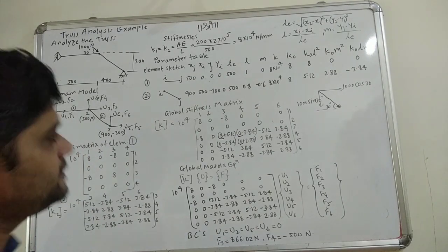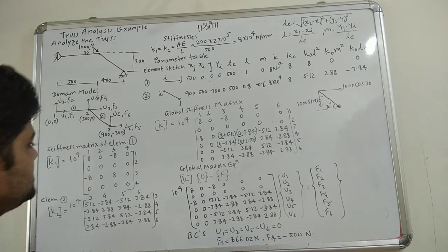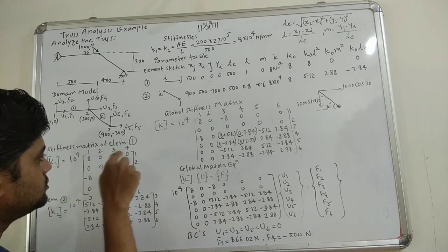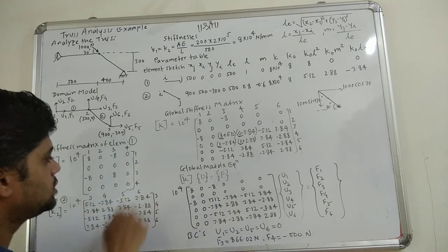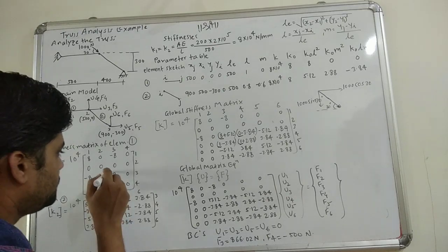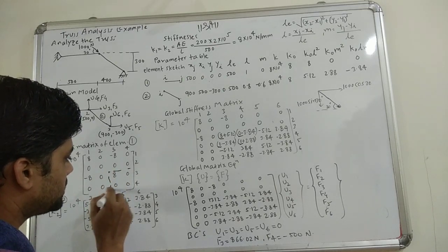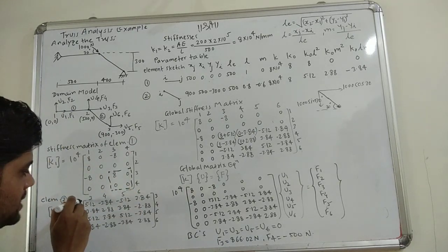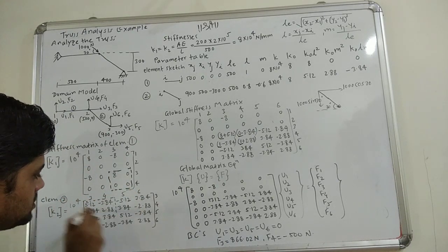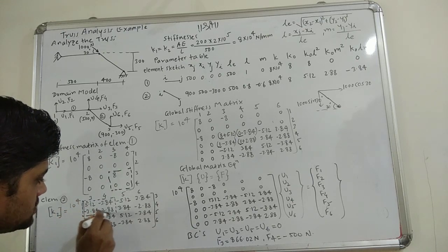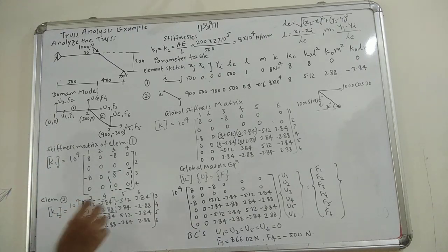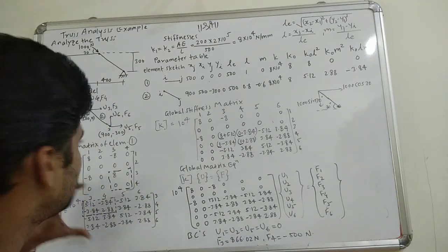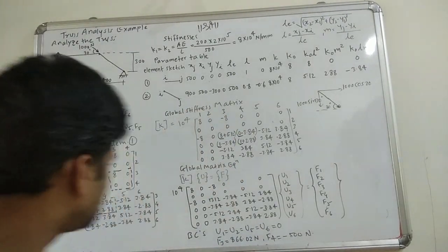Now if you carefully observe these locations, the third row and fourth row, third column and fourth column, you can easily see them. I'll just square them up, and this square matrix, this stiffness matrix, these are the overlapping elements of the stiffness matrix inside the global stiffness matrix.